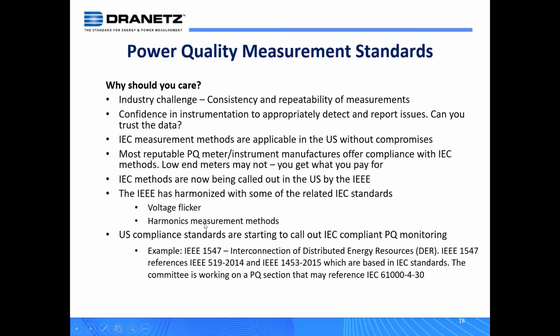A big example in the United States is IEEE 1547, which involves DERs, or distributed energy resources. This is the interconnection of DERs, which are wind farms, solar farms, any other alternative energy, to the grid. And they already refer to monitoring based upon IEC 61000-4-30. We understand future revisions will become more ingrained with the measurement capabilities of the instrumentation being used to monitor. So there's a whole thing of interconnecting to the grid to make sure that's a reliable power source and it's not creating power issues for the utility, or vice versa, actually. They're defining standards to monitor, and we're referring to industry standards to monitor for these things.